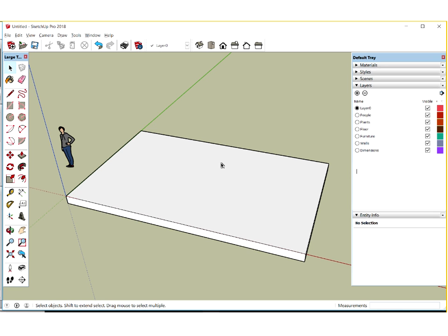I think, even for a large project, a layer list shouldn't get too long. If you're doing a whole hotel or something, you'll probably end up with 40 layers. But you don't really want more than that. You want a visible list that you can scroll through and just separate things into simple families. And we'll look at why that's important in a minute.